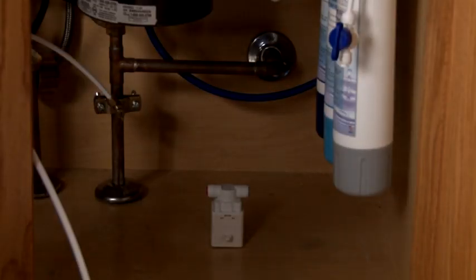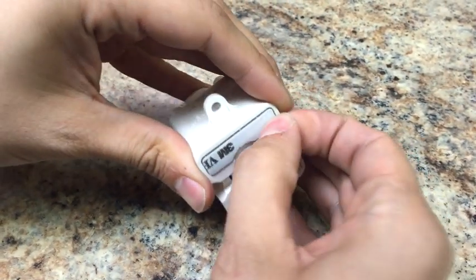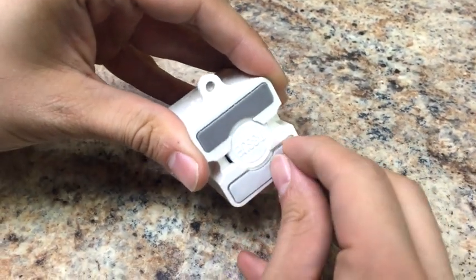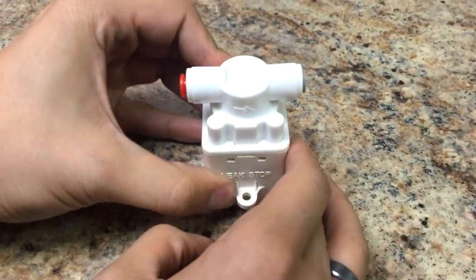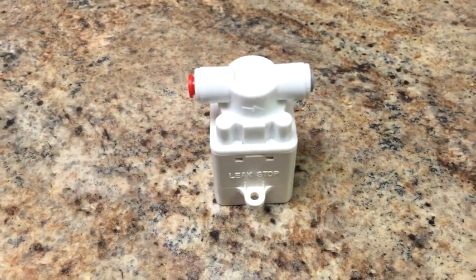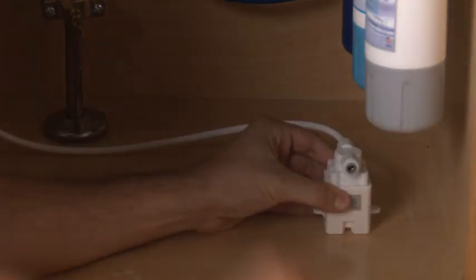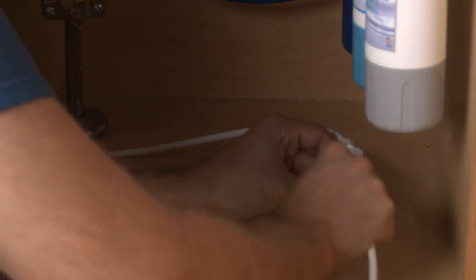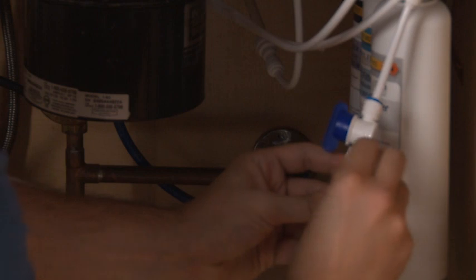If the unit is installed under a sink or where damage could occur due to a leak, be sure to install a leak detector with automatic water shutoff in the supply line. Mount the leak detector to the floor of the cabinet directly below the unit. Note the flow direction markings on the top of the detector. Should even a slight amount of moisture contact the bottom of the detector, the water supply to the RO will be terminated. If the leak detector terminates the water supply, merely fix the leak and reload the detector with a new sensing pad that is stored inside the detector housing.